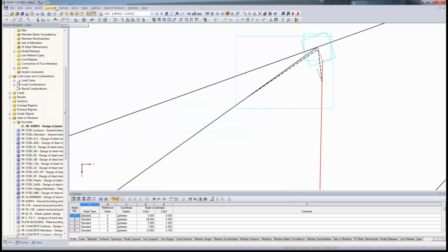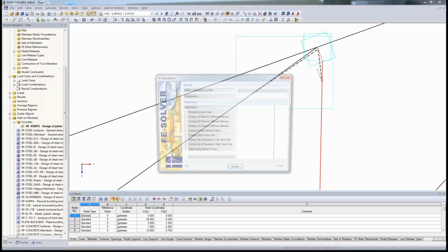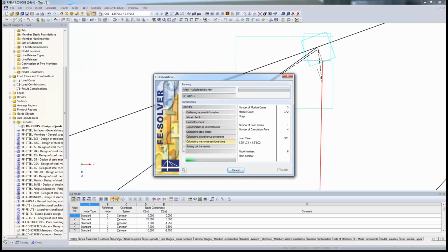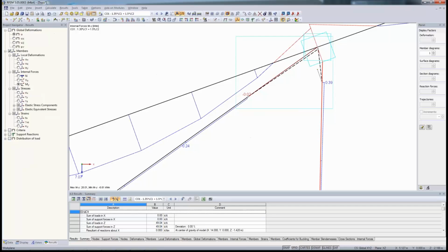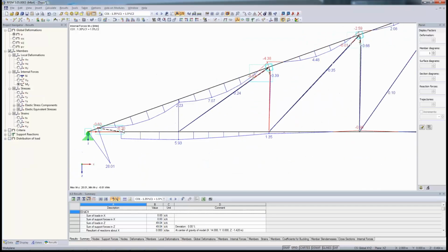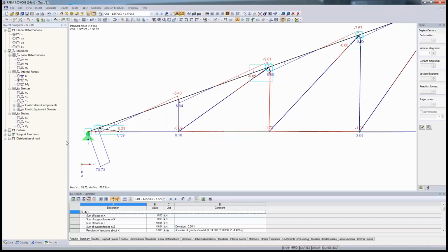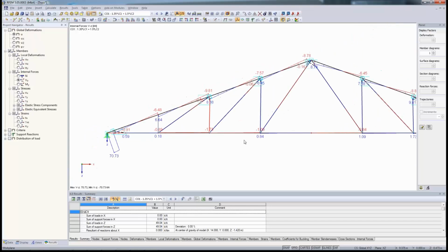Now if we calculate the whole position and look how the loading goes up, we assume that the loading of the connection goes up, because if you look for the resulting force for the moments and also for the shear force, you see that in the field the moment is lower, which means I have less load bearing of the beams, but I have more load assigned to the connection. So you see we have here a high peak of moment that's actually assigned here, and you have for sure also a high shear force, because you have just the little cantilever from this support to this support, which is also a pretty high jump.